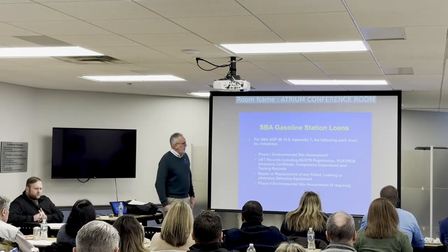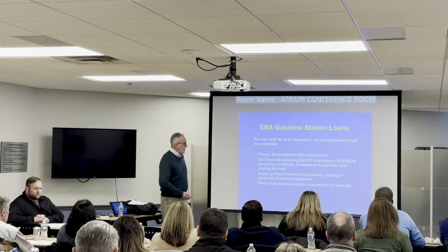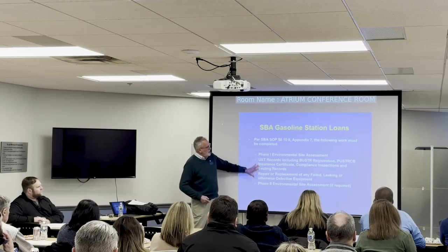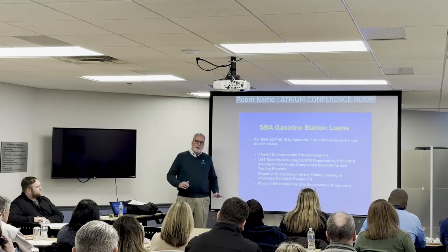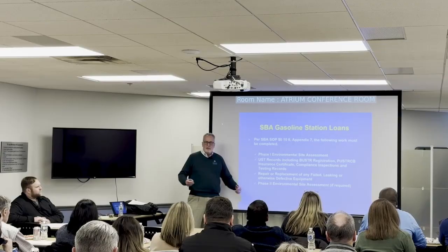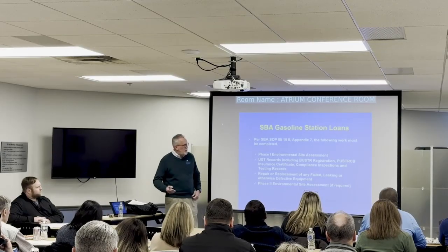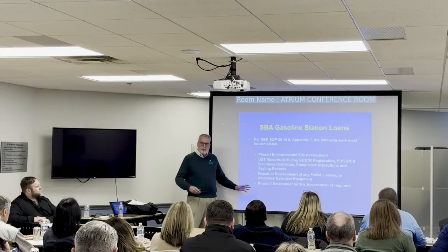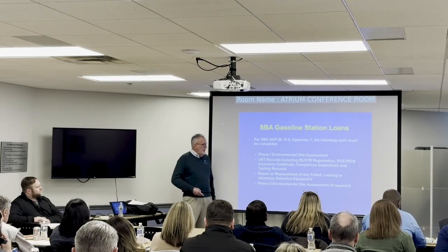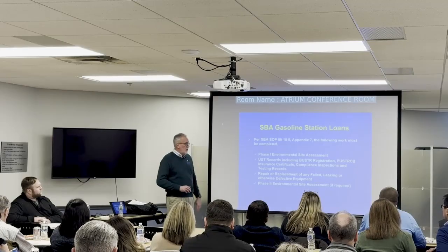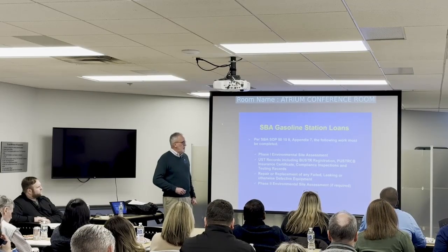And then a phase two environmental site assessment if there's something that requires additional work. We just did a gas station site where all these records were good, but we had an older environmental site assessment that showed where a used oil tank and a heating oil tank was removed behind the building, no closure on that. So we went in and did a geophysical survey. We'll talk about that in a minute, and collected some data from that site in that area, not associated with the ongoing current underground storage tank system.